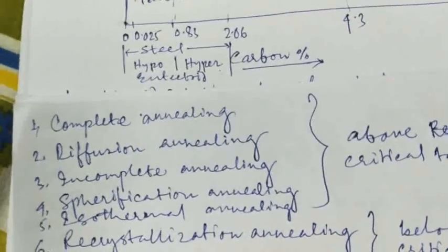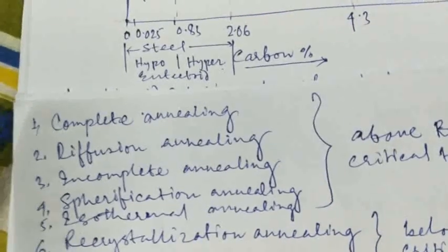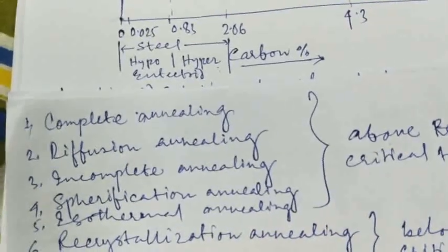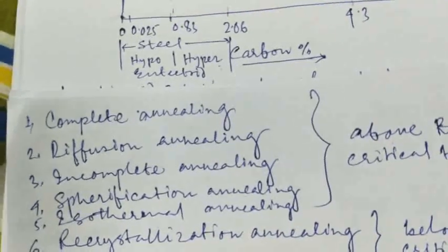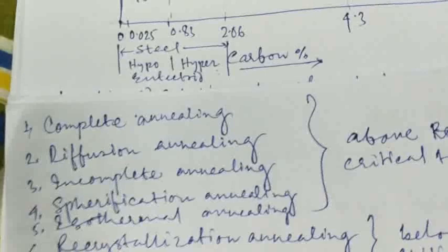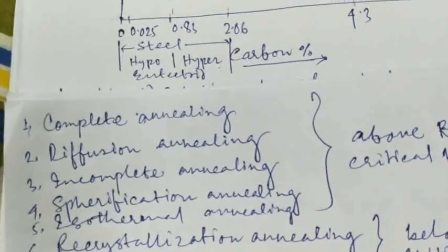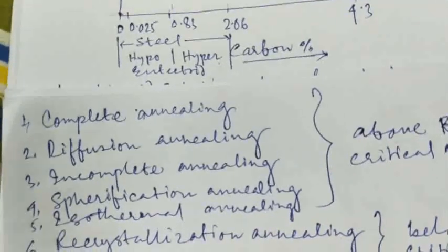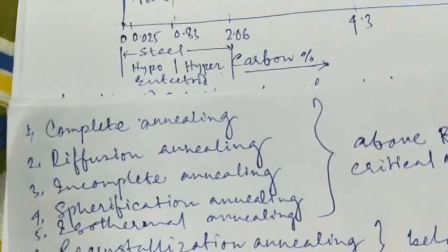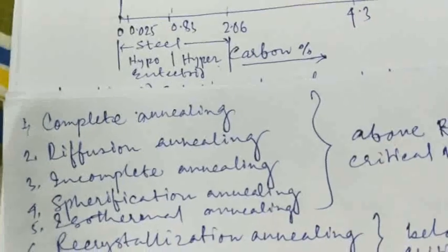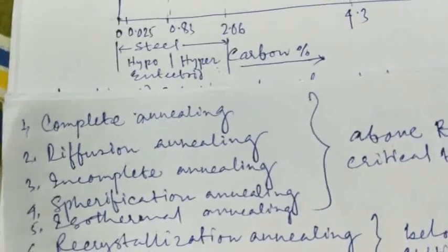Third, to eliminate internal stress and process hardening to prevent deformation and cracking. Annealing and normalizing are mainly used for preparing heat treatment. For parts with low stress and low performance requirements, annealing and normalizing can also be used as the final heat treatment.